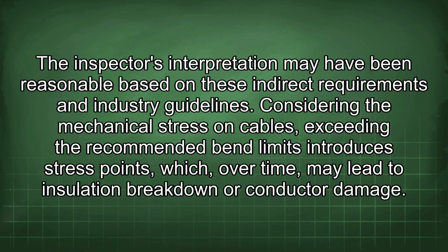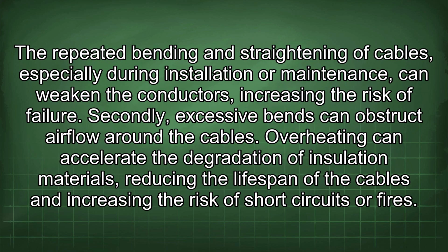Considering the mechanical stress on cables, exceeding the recommended bend limits introduces stress points, which, over time, may lead to insulation breakdown or conductor damage. The repeated bending and straightening of cables, especially during installation or maintenance, can weaken the conductors, increasing the risk of failure. Secondly, excessive bends can obstruct airflow around the cables. Overheating can accelerate the degradation of insulation materials, reducing the lifespan of the cables and increasing the risk of short circuits or fires.